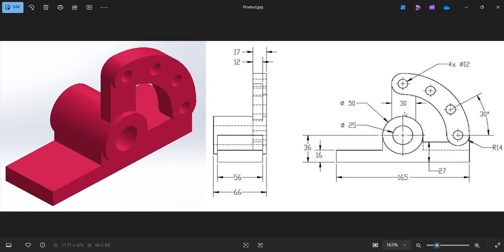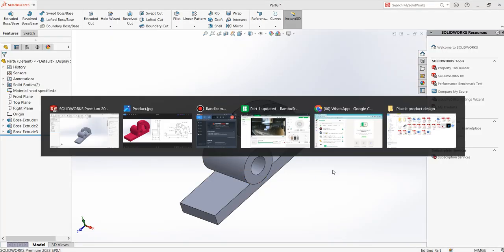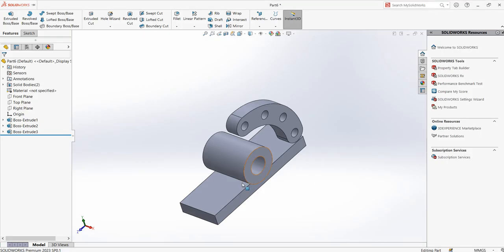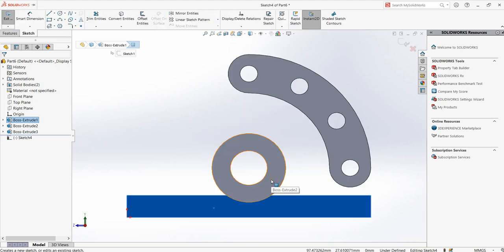Okay, now what is left is this center piece here, which is 30 width. I can see from this isometric view it has to be connected. So I can form that from, since it's going from this plane, so this is actually lying on this plane. Let me make a sketch on this plane. Click and say new sketch.